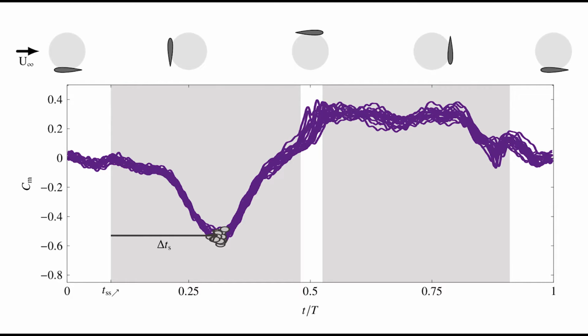In the upwind half, the dynamic stall delay was found to be 3.4 convective times on average, based on the blade's chord and velocity. This falls right into the optimal vortex formation time, found to be between 3 and 5 convective times for symmetric airfoils. In the downwind half, the blade only has 1.3 convective times to form a dynamic stall vortex, which is insufficient.